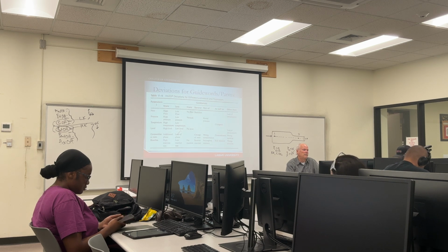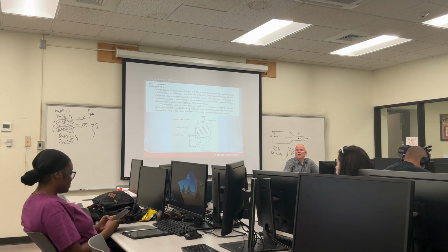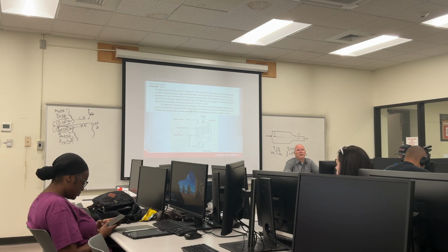And then, here's an example of a HAZOP that they have in the book. So we've got a reactor system, an exothermic reactor. The design intent of the cooling system is to remove energy. Obviously, if the cooling function is lost, the temperature increases. That increases the reaction rate, and then more energy results, and the ultimate result is runaway reaction. So that's clear, that's for pretty much any exothermic reactor that you've got.